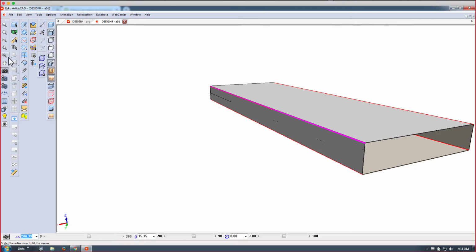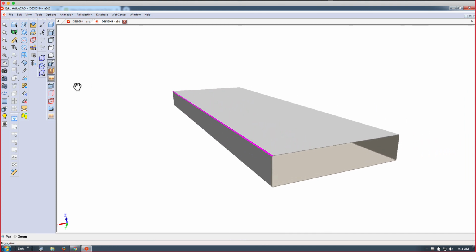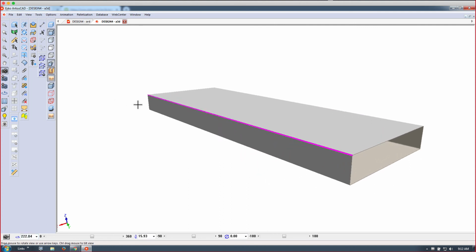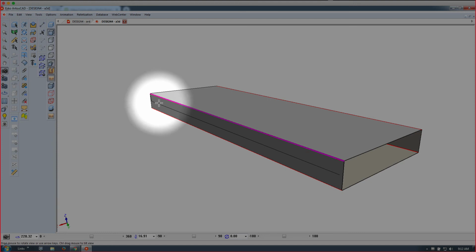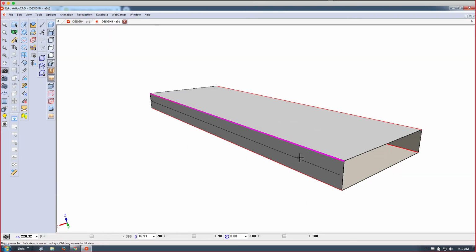And here I'd like to draw your attention to, let's zoom in a little bit again and use the camera view angle. You can kind of see here all along this panel that my one fold for my glue strip, which was set to 90 degrees, coincides with the same angle that was set here on this view. So we essentially have two panels that are fighting in that same Z-plane.